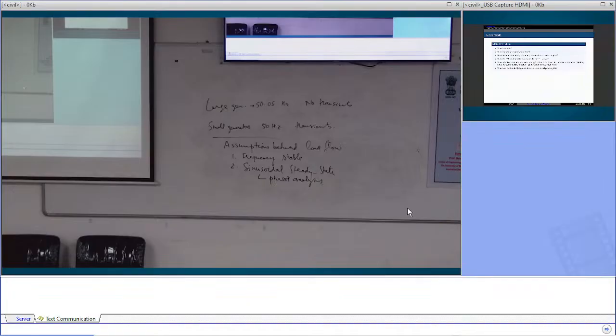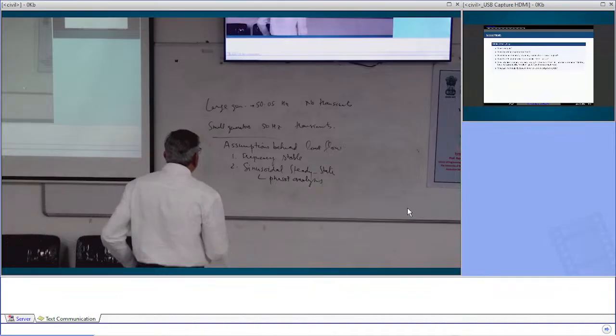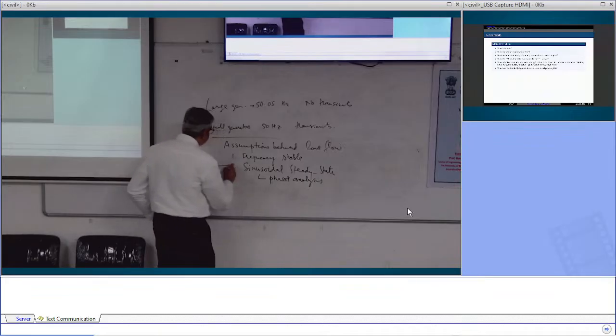Algebraic equations. And you said L di by dt, somebody said S. That's a very big thing to solve. How many inductors and capacitors will be there? Hundreds of thousands. So your equation order will be a few hundreds of thousands, differential equations, if you want to do that. When you do it in phasor analysis, equivalent inductance, equivalent capacitance, and you are home. Algebraic equations. So that's a very powerful tool, but it all depends on sinusoidal steady state.